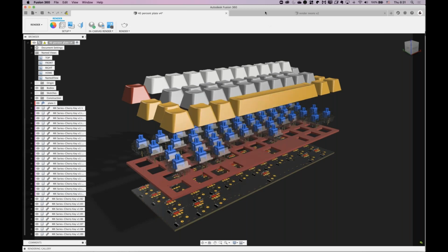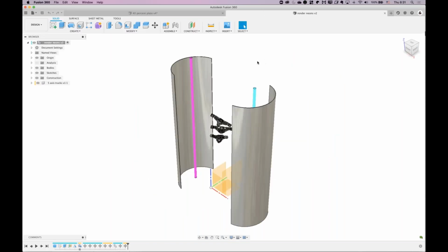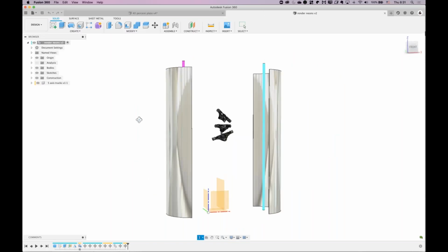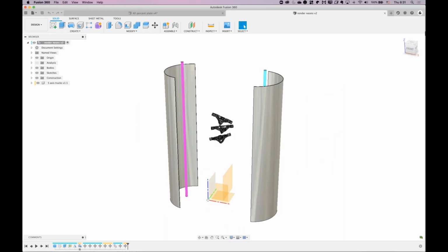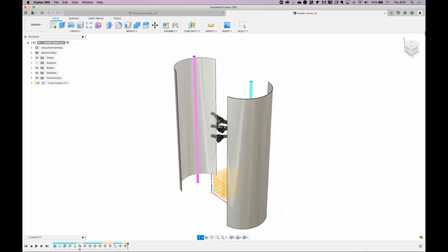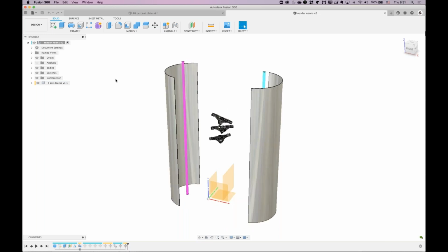One of the other ways that you can work with rendering in Fusion 360 is to create custom lighting. In this example, in the modeling environment, I've treated the model space like a photo studio. So I've included 2 light bars here. These are set to neons, and behind them are these mirrored arcs, which are designed to bounce the light back in, just like you would see in a regular photo studio.